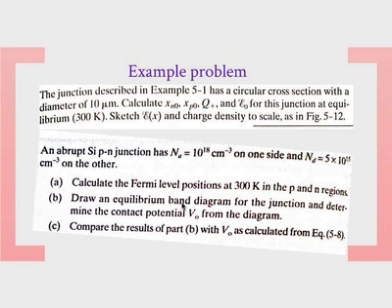So we don't need to actually work through this, because I'll work through this quickly, so we don't waste a lot of time. Essentially we have the acceptor concentration here, we have the donor concentration here, so we know we have a transition region here. This whole width is W, this is xp0, this width is xn0. You should be familiar with these notations, but if I ask you a question, I will make it obvious what it is. Okay, so first calculate xn0, xp0.